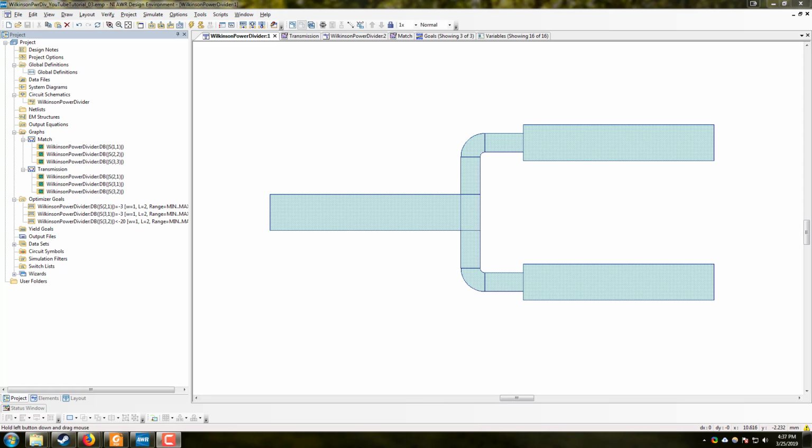And so as a result, if we want to have as close to 100% accuracy, as close to real world performance and the idea of how this component is going to behave, we need to do an electromagnetic simulation. We cannot do a circuit simulation. That starts introducing assumptions and things like that. And so we need to do the electromagnetic simulation. This is going to give us the best estimate of how our component is going to behave in the real world.